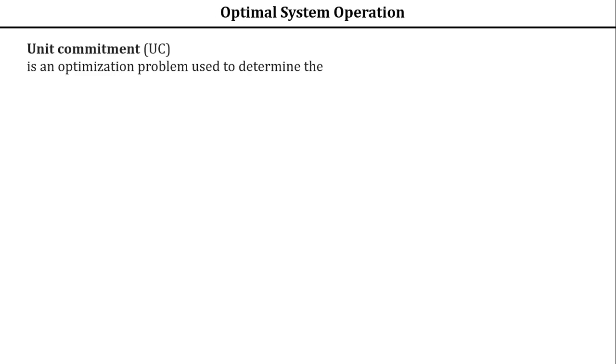Say a particular load has been given. For that load, use the coordination equation which I explained in economic operation. You know what the coordination equation is? Solve it for a particular load during the given time. Again, the load will vary continuously; it will not remain constant. Whenever the load varies, again solve the coordination equation for all the 7 units. For the next change in load, again solve the coordination equation for all the 7 units. This process you have to repeat till you get an optimal cost.